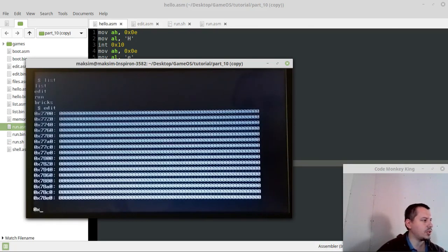We want to start with the address 7700. So I type the address 7700, and then these bytes: B40E, I can make a space, I can not make a space, it doesn't matter. B40E, B048. If I don't type this correctly, I would just restart from scratch, because even though it's possible to fix, as I've mentioned, calculating the proper offset takes ages, so it's really easier to start from scratch. That's just from my experience.